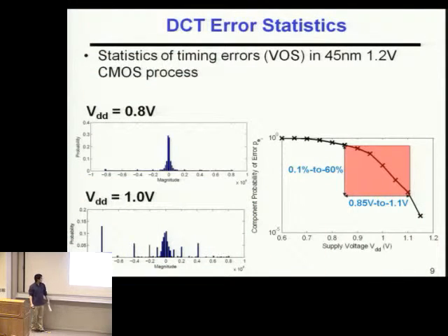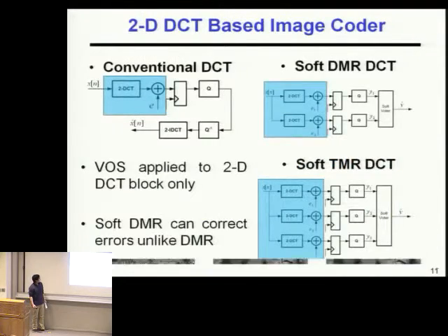because most computation is done LSB first, so your most significant bit would be the last to complete its computation. So timing errors are circuit making errors because there isn't enough time to finish the computation. So when you have timing errors, they are mostly in the MSB. So it's not exactly a Gaussian distribution. And this is one of our research topics that we are looking at.